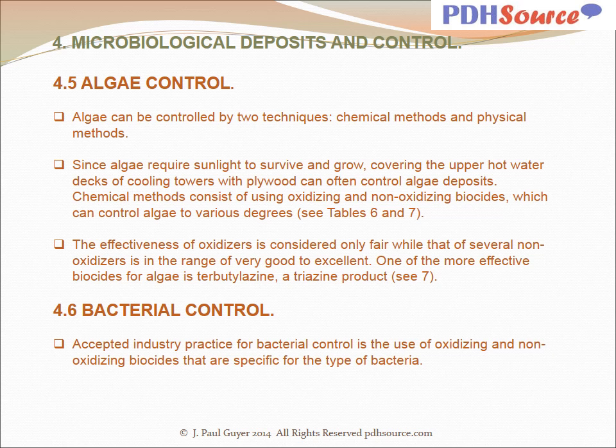The effectiveness of oxidizers is considered only fair, while that of several non-oxidizers is in the range of very good to excellent. One of the more effective biocides for algae is terbutylazine, a triazine product.